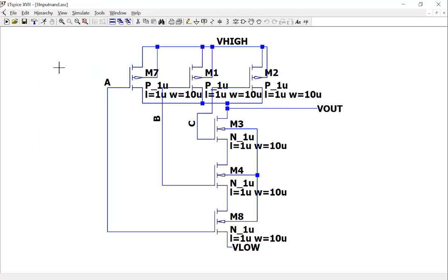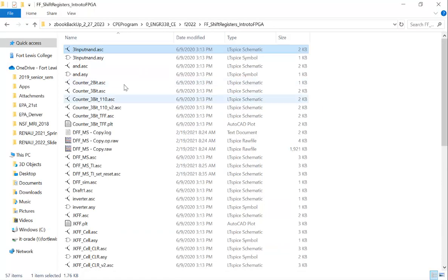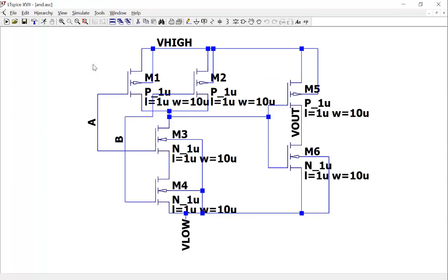Okay, starting from transistor level circuits. You've got a V high and V low as ports, because they need to be powered up and grounded. That's 3 inputs, 1 output. And similar for the 2-input AND. For the AND gate, you need a NAND gate and 1 inverter here. It should be easier this time because you have learned all the stick diagrams and the circuits. You know where to connect, instead of connecting to any of the random ports in Logic. I see all the weird connections in the circuits in Logic because they didn't know what was going on in the circuit.